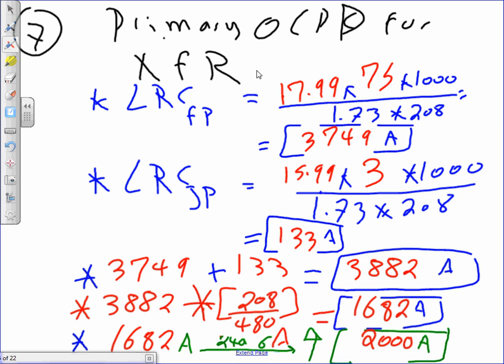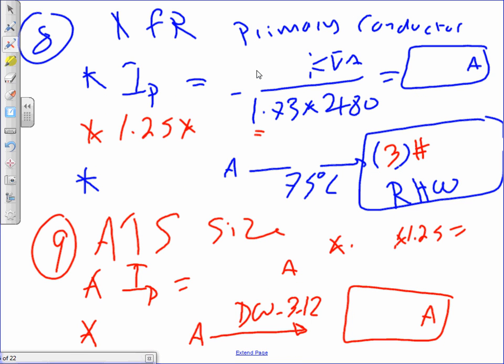Okay. Shall we go to the next one? The next one, guys, is the primary conductor. Here's my 100. Find the full load current for the 100 on the primary side, Adam. You get 120. Do me a favor: here's one step I don't want to use. Directly, I don't want to multiply again by 1.25. Can you guys cross this step? I used to multiply, you know why I didn't? Because when we sized the transformer, we already multiplied by 1.25, you remember? So I'll take the 120.